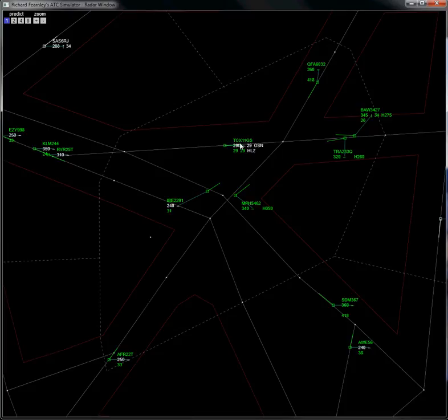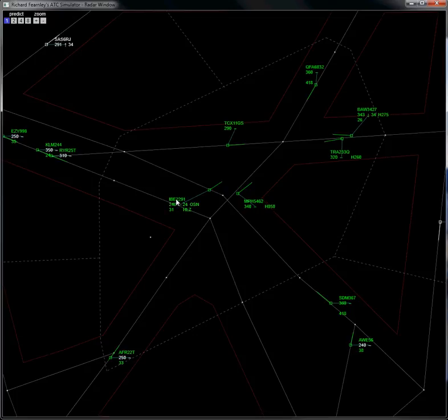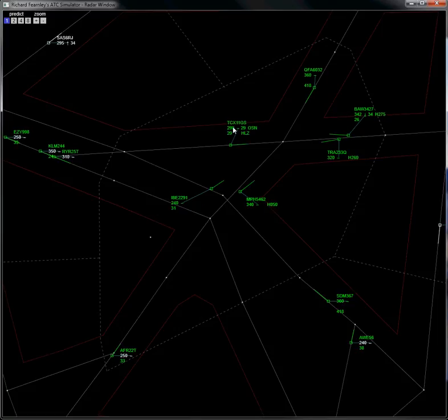So also this aircraft that's in my sector, I assume the label turns green. It's a Kestrel 11 Golf Sierra exiting my sector at flight level 290. But I also have this Iberia 22901 that is also exiting at Hotel Lima Zulu, which is a point over here to the east. This one is requesting flight level 310. It will create quite a lot of work for me to get this aircraft above the Kestrel 11 Golf Sierra, so I'm going to swap the planned flight levels.